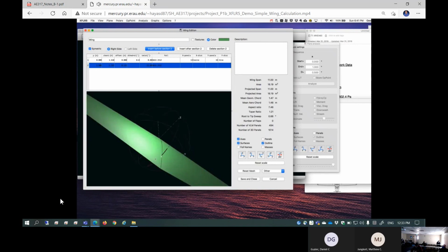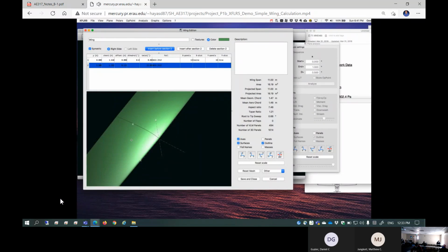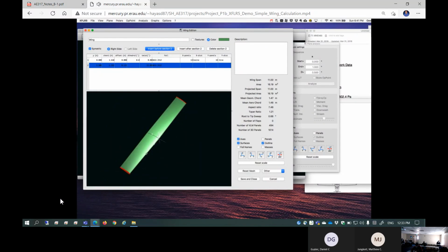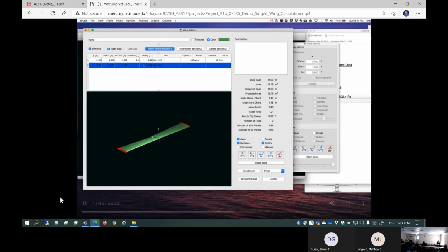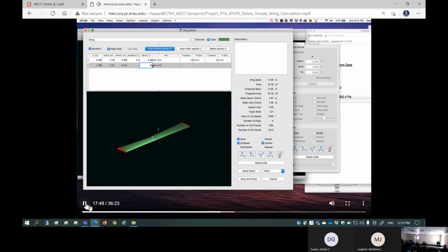Washing out has some advantages we'll discuss a little in class having to do with stall characteristics. When you do your projects, it might also give you some advantage in minimizing induced drag. We are going to put 0 in this case, to mimic the actual wing, which has 0 wash. Obviously, if you put in wash out or wash in, how do you create the wing out of styrofoam? It's a nightmare to hand cut styrofoam with a twist. However, in reality, every airplane needs to have a washout.